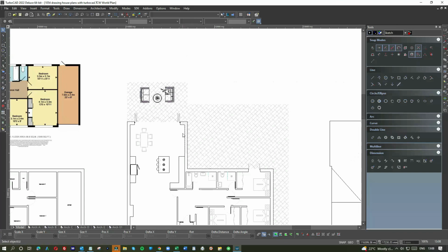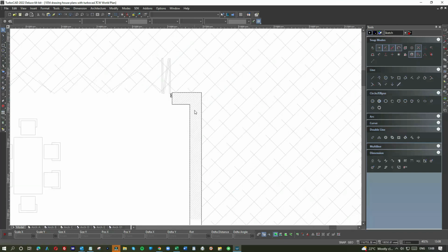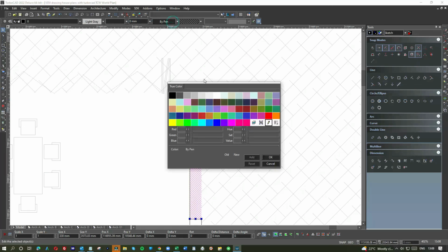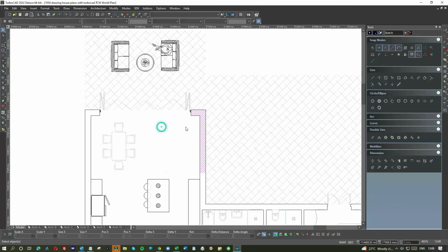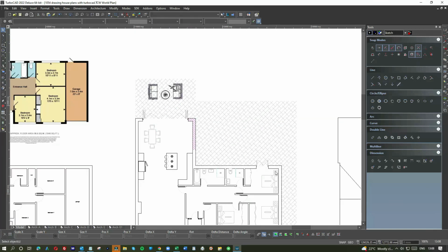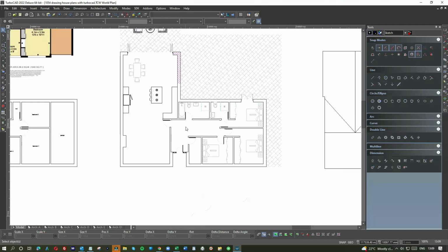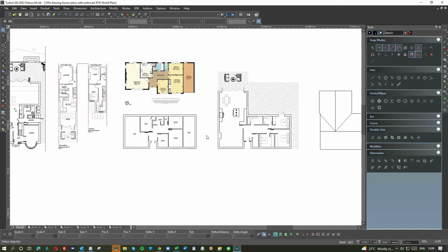And you know, again, sometimes I'll use a pink. In fact, I'll use a magenta to show new walls. In other words, I do it all in grey, but where the walls are new, it'll help the planning officers and the builders and so on to instantly see what the new walls are. Sometimes when I'm going from existing to proposed, I'll leave an outline which is dotted lines to represent the old walls, and of course I can do that using layers, which means I can show or not show them at the flick of a mouse.